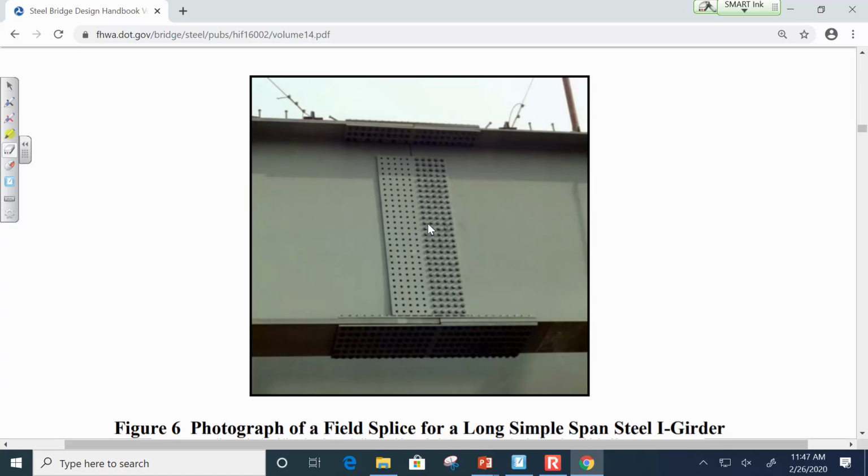Now, we are doing basic bolted connection design in this course. The design of a spliced connection is very intricate because you have to design it for axial load, shear, bending, and block shear. Every connection-related issue you could think of is in this connection. So they're very, very difficult to design.